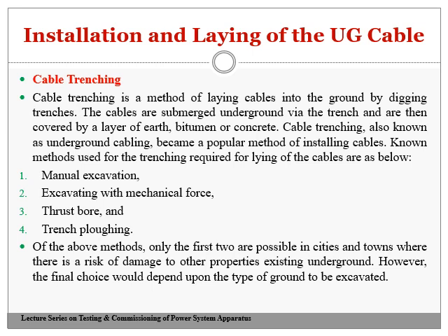Now here, once the cable laying is done, depending upon the number of cables, those are placed in a proper way, or maybe in racks in the trench. Then afterwards, this is covered by a layer of earth, bitumen or maybe concrete. The cable trenching is also known as the underground cabling process.